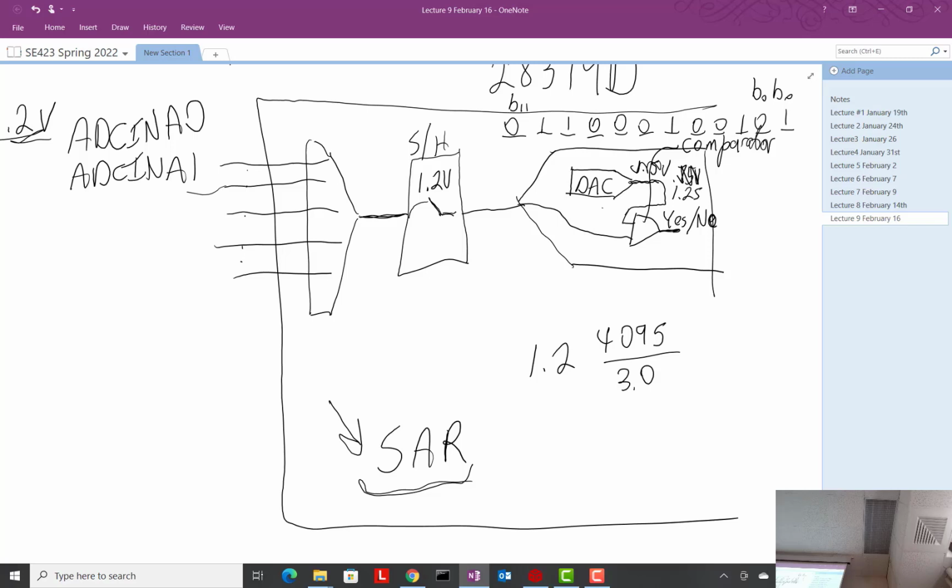The ADC will then go through this process, and it actually may do a sequence of channels. We can set up a sequence so that it samples ADC in A0, then A1, then A2, and actually we could do it in any order. We could tell it to sample ADC in 5, and then 1, and then 4, whatever sequence we want. We'll explain that sequencing. But the issue is, we tell it to start, and then it does its conversion. When it's done, it'll cause an interrupt to occur, and inside that interrupt, we then read the results.